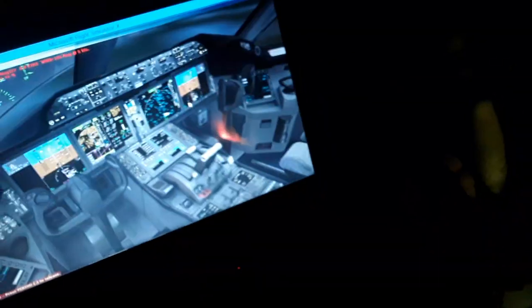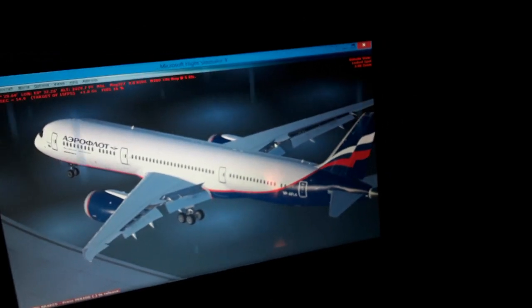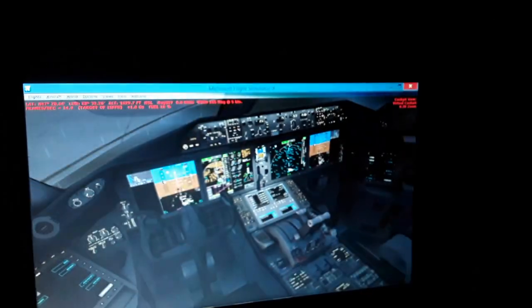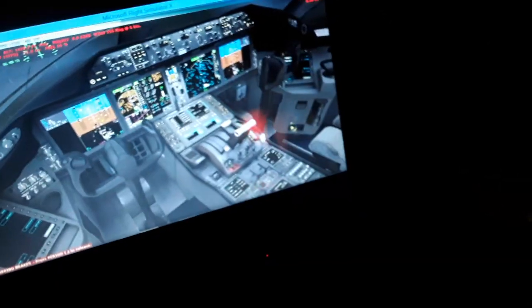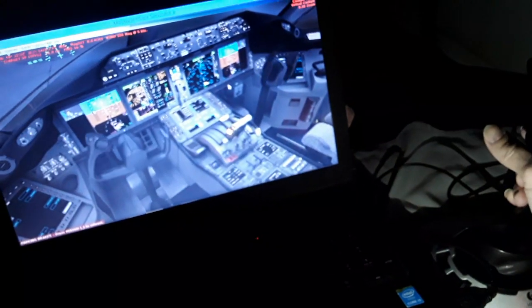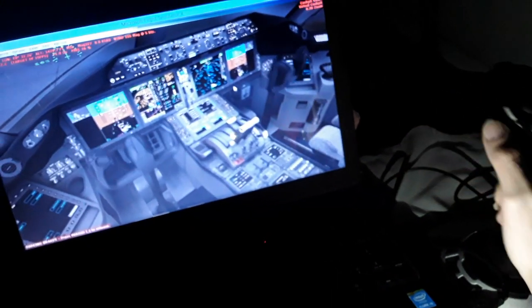So the valves and the bleed air from the bypass stage of the fan supply other systems like the hydraulic fluid pressurization tanks, and all the flight controls movement you see here, like in the wings, the rudder, the elevator, as I showed you, ailerons and spoilers. All these need hydraulics to function. So this needs hydraulic power for the control surfaces.